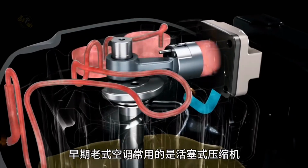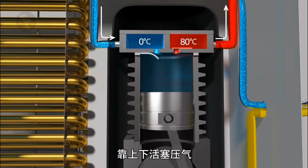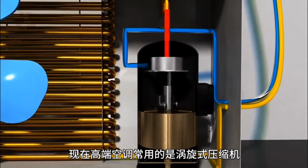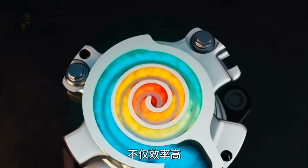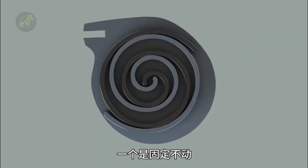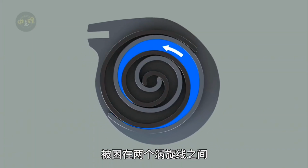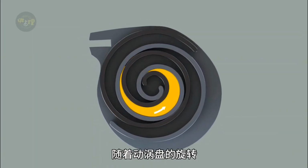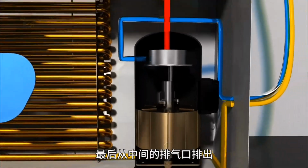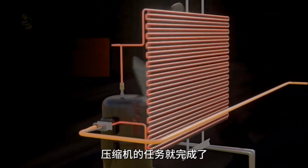Early old-style air conditioners commonly use piston compressors, which operate like car engines, relying on pistons moving up and down to compress. Piston compressors were noisy and inefficient and have now been mostly phased out. High-end air conditioners now commonly use scroll compressors, which are not only efficient but also quiet. It has 2 spiral shell-like scroll plates. One is fixed and the other moves around it. After the gas is drawn in from the outside, it gets trapped between the 2 spiral lines. As the moving scroll rotates, the gas is gradually compressed towards the center, increasing in pressure, and finally expelled from the central exhaust port.